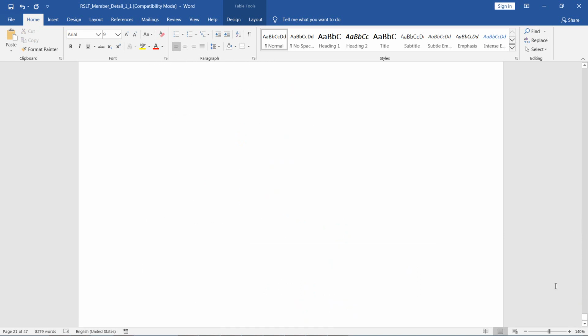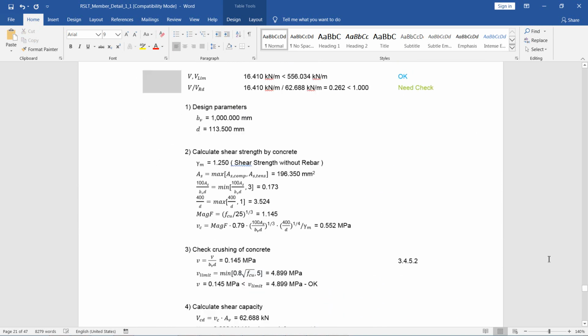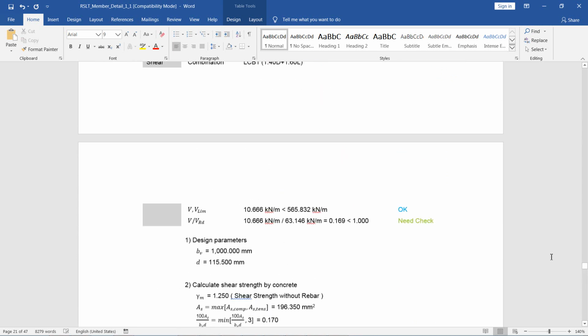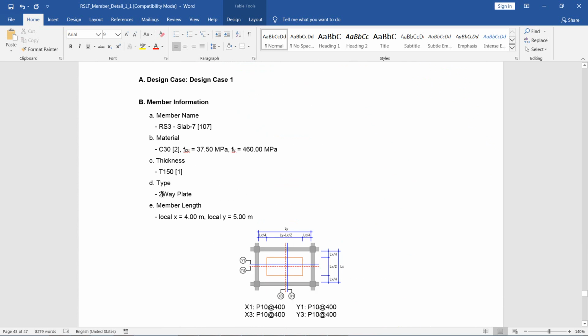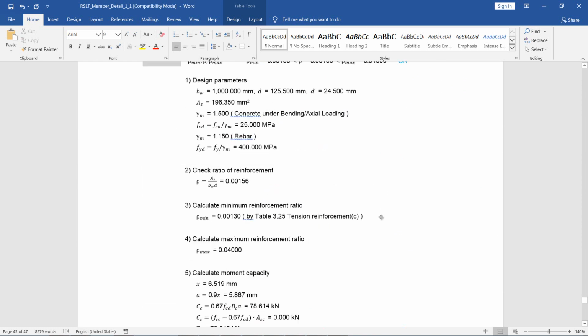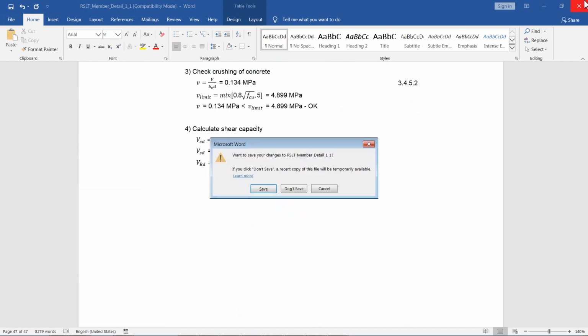So if you have got a slab which is irregular in shape or has got a shear wall in between, then the design will be based on the default design parameters that have been provided. So this is a two-way plate type. You can choose if it's a two-way or one-way plate type likewise, but plates are usually two-way. And the design is performed, check is critical. Yes, so this is how the detailed report is generated using MIDAS nGen software solution.